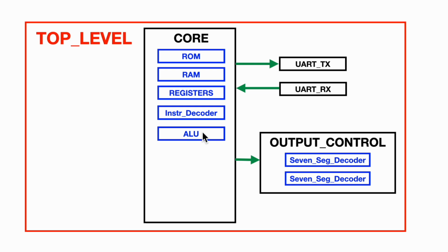And finally we have the ALU module. This is also combinational. It takes basically 2 8-bit inputs, and these will come from the A and B registers, and it produces an 8-bit output. It also takes as input a function code and the previous value of the carry, and it produces also the future value of the various condition code registers.